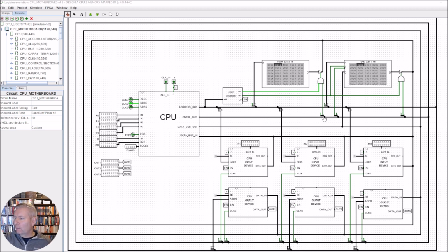So we have to connect onto this bus. We connect onto the bus using these little connections here, the splitters. So that's what all these little connections here are. They're splitters, allowing us to get into the bus and pull off the correct wire from the bus that we require. So in this instance here, it's only a 2-bit bus, so we've only got 2 outputs, a 0 and a 1. So the 0, 1 here is actually the enable. So whenever that enable goes high, it means we're going to have a high here, and we're going to pass this data from the ROM onto this bus.